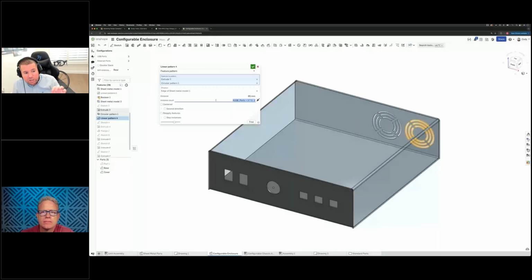And it's hash symbol USB ports greater than 3, question mark 3, else 2, colon 2. And so the way to interpret this is the configuration variable USB ports, if it's greater than 3, then this value should equate to 3. If it's not greater than 3, it should equate to 2. And so these two are the potential values for the instance count, and this is the expression used to define the total number of instances based on another factor, in this case, USB ports.